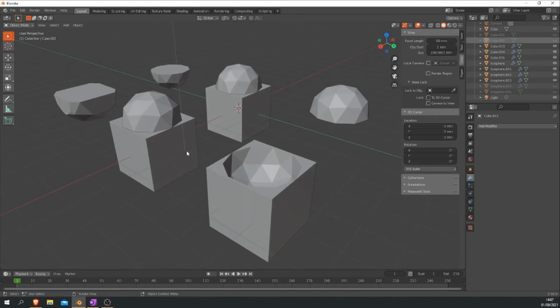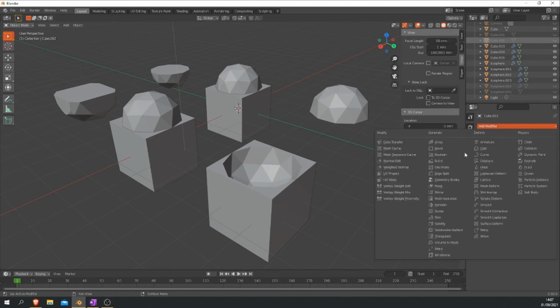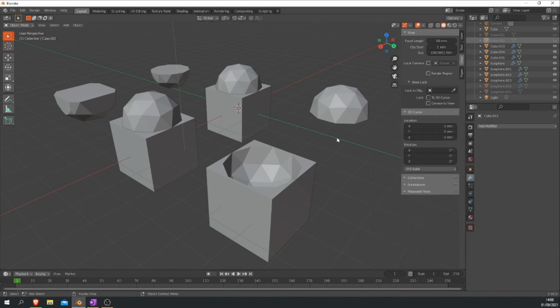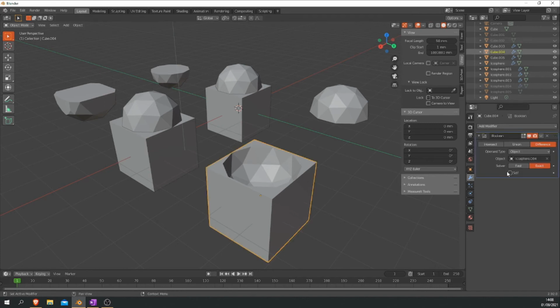So I mean, with a couple of different shapes, you can get 6 different ways of modeling with one modifier, and it's really good for taking parts away from a model or looking to join two parts together. There is a little bit of a learning curve with it. I think that union is pretty okay. You just click the two parts you want to join, and it joins. The intersect is a bit more difficult. You've got to play around and wrap your head around it so that you become comfortable using it, but it is easy once you know what you're doing. So I wouldn't worry too much.